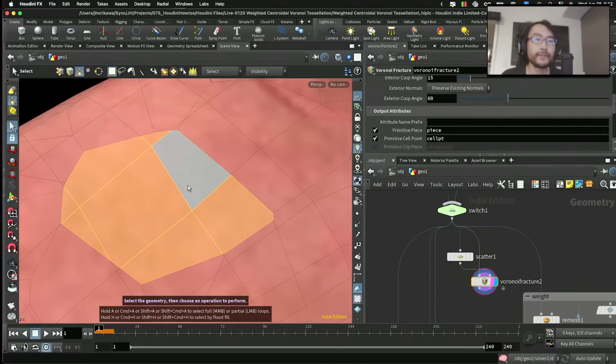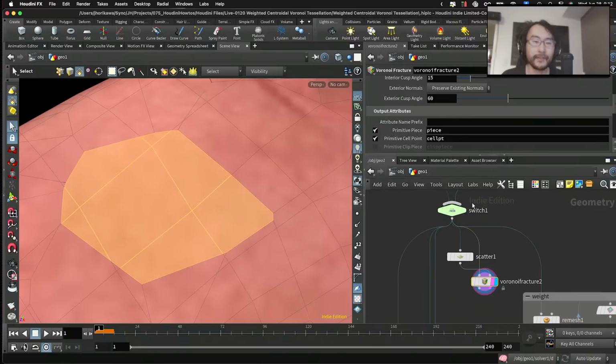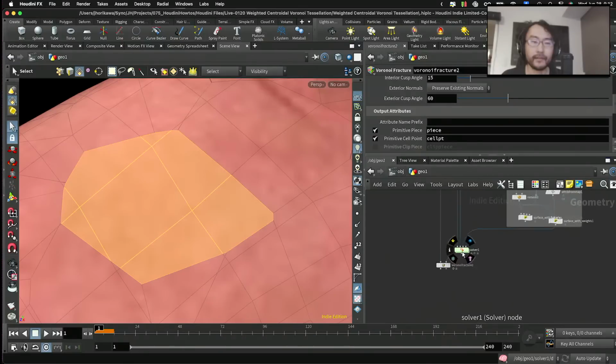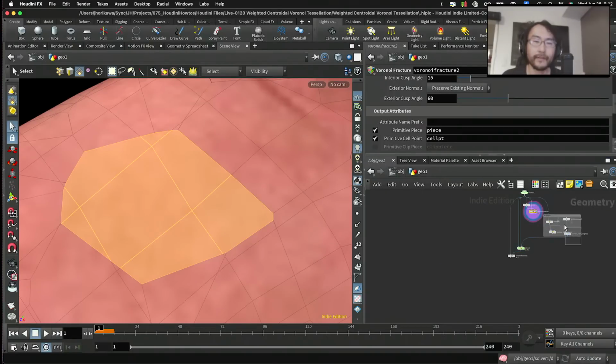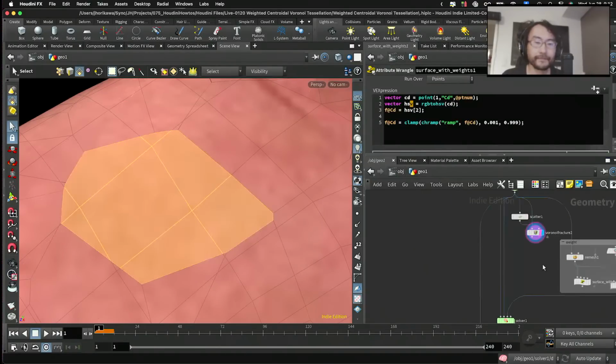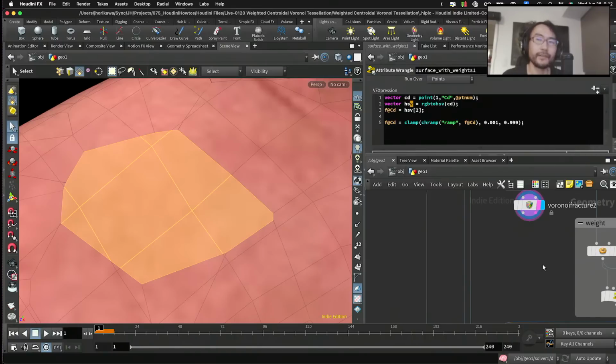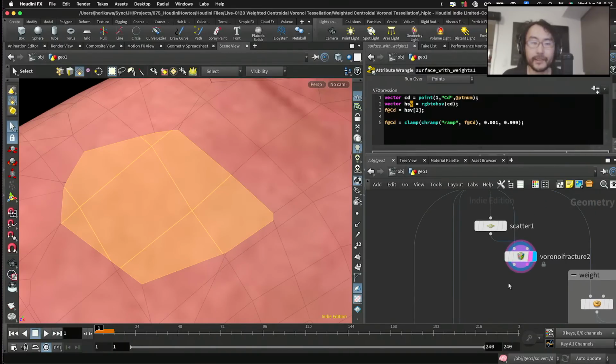And what I need to do is to calculate the centroid of this geometry by dividing every primitive into triangles, just like I did previously, and recalculate the centroid based on the weight I have here and create a new centroidal information.